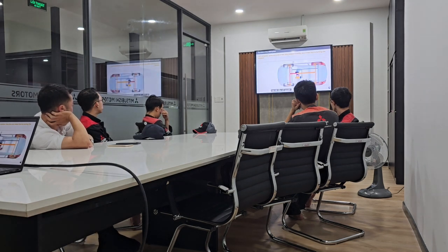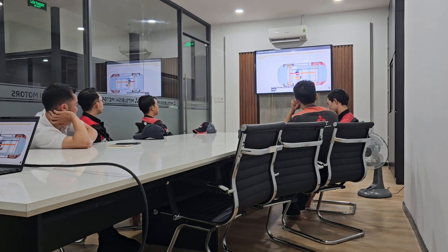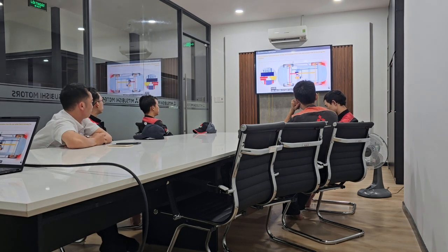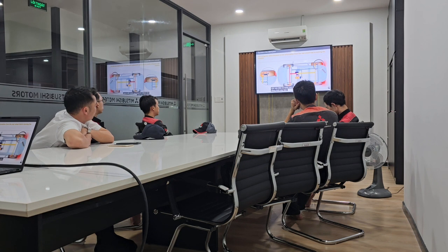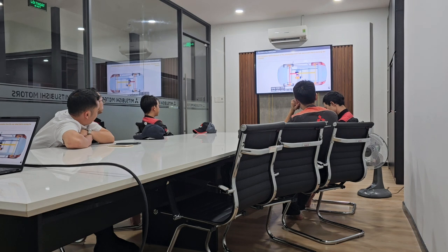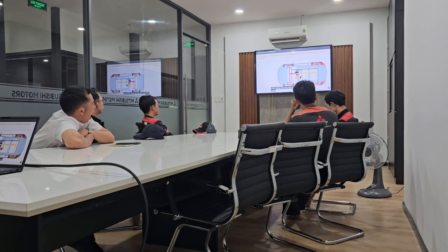Let's start with the principle that the rear axle must be braked using a force which is lower than the force used for the front axle. The rear wheel solenoids are controlled simultaneously. The computer uses the electronic brake distributor logic to do this. The computer takes account of the information from the rear wheel that is turning slowest. This computer function is called select low.